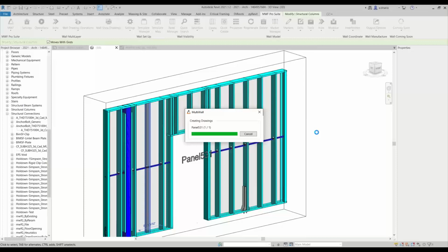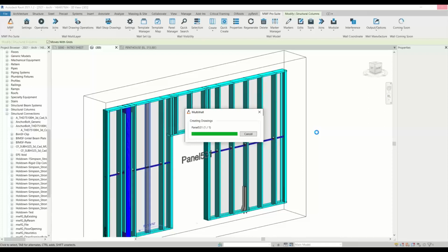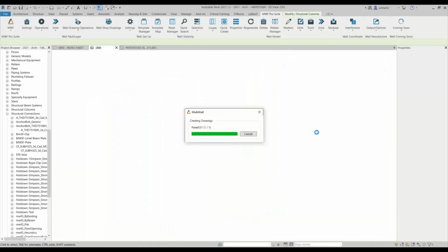These shop drawing settings are currently copying an existing schedule. I'm using an existing Revit schedule as a base for all my shop drawings, basically as a template, so that they can grab the formatting and parameters from that specific Revit schedule.